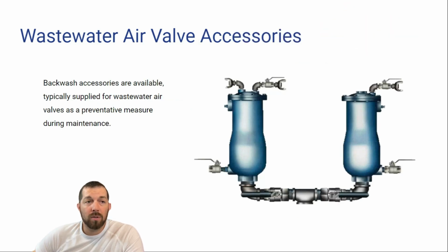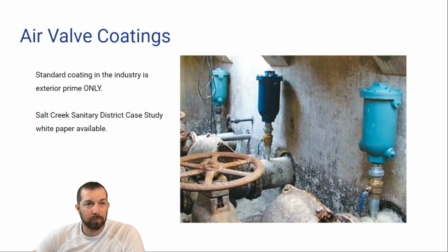Wastewater accessories, the most common is the backwash accessory kits. These are typically supplied for wastewater air valves as a preventative maintenance measure for the operations to basically keep these clean and functional.